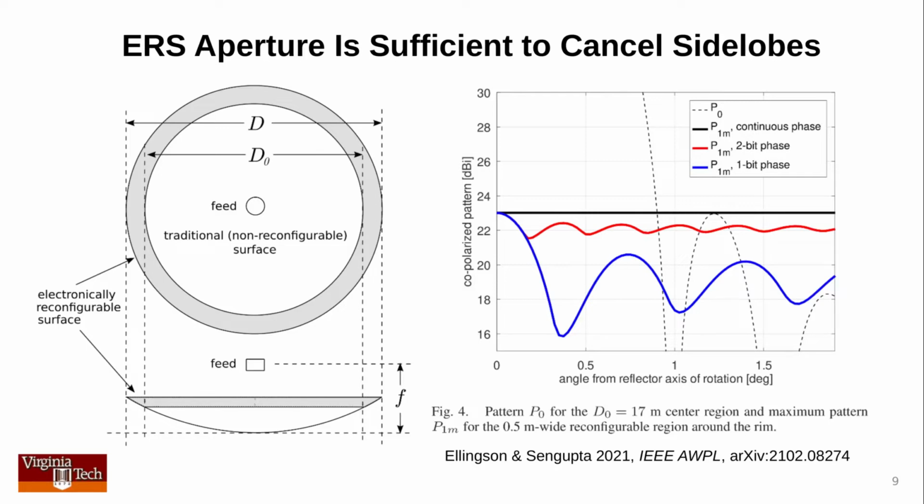You can see that you can easily overcome the second and subsequent side lobes, and that with sufficiently fine control you can overcome parts of the main lobe and the first side lobe. Now, note that these are pessimistic estimates, since we are not actually trying to maximize gain in some direction, but rather minimize the gain of the sum of the main reflector and the 2,750 elements, which is not exactly the same thing. But we'll demonstrate that in a moment.